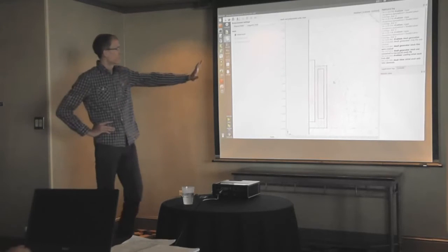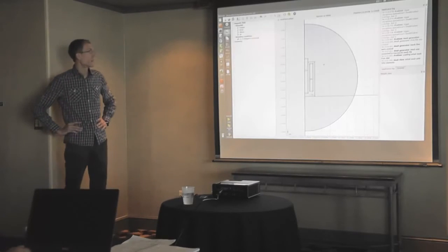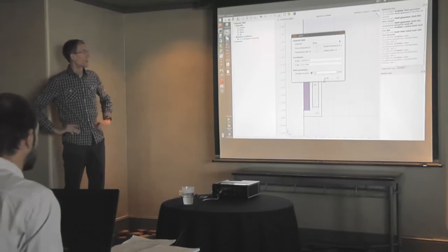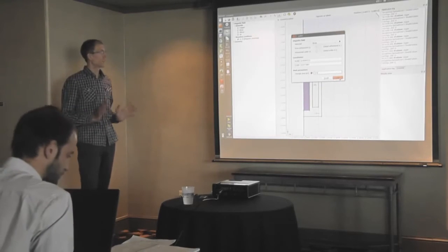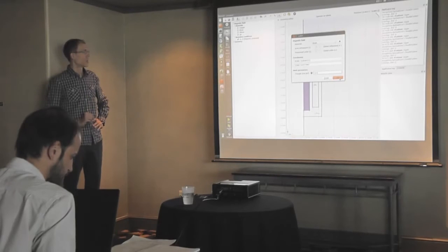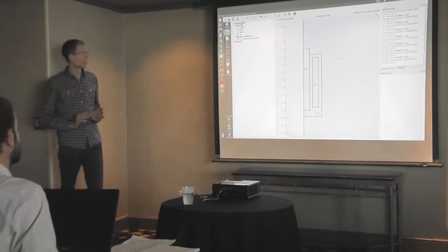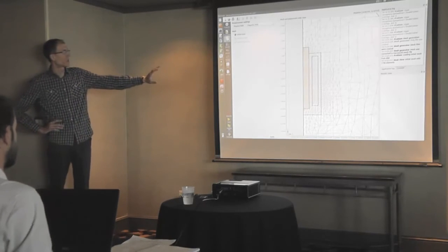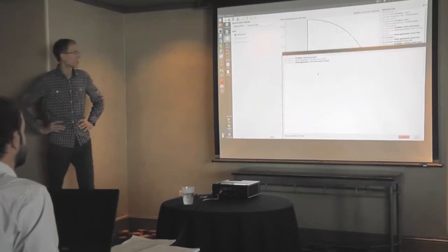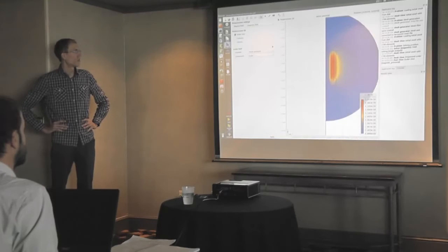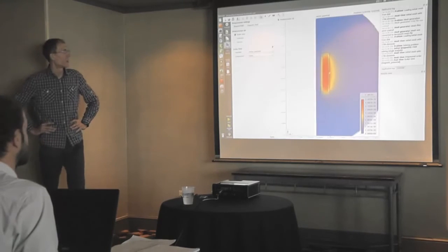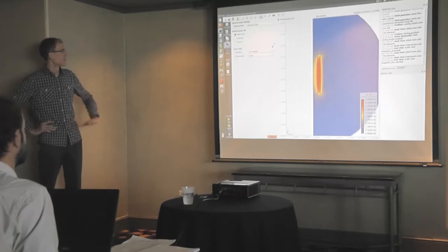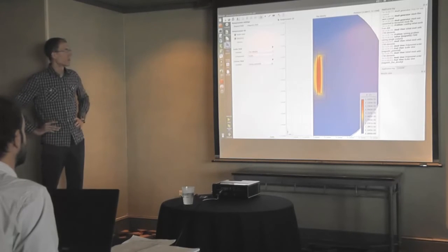Now we use Triangle to create a mesh. We can also adjust how dense the mesh should be in each area, and also make it refined towards some boundary. So we wanted a finer mesh inside the armature, which has been done now. Now we solved the problem, so far only in the magnetic field. Now we can display flux density or other post-processing features.